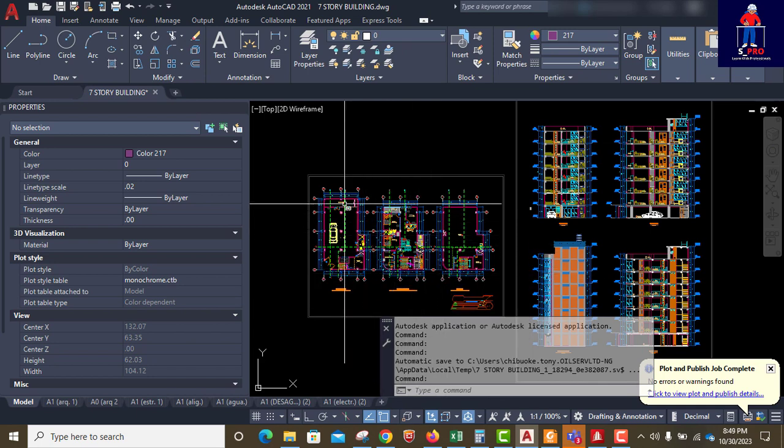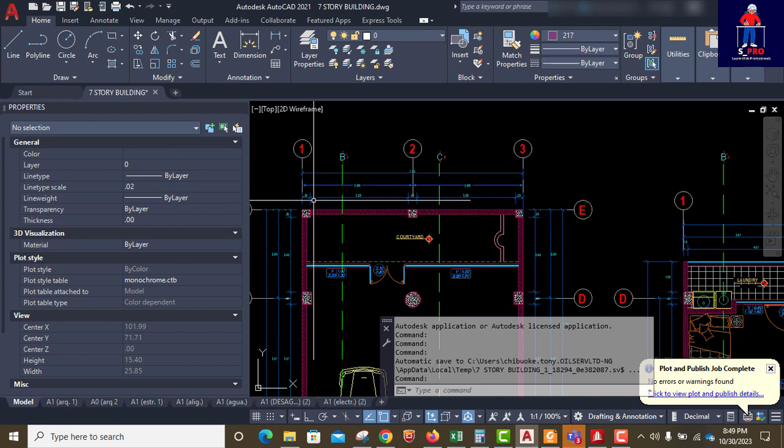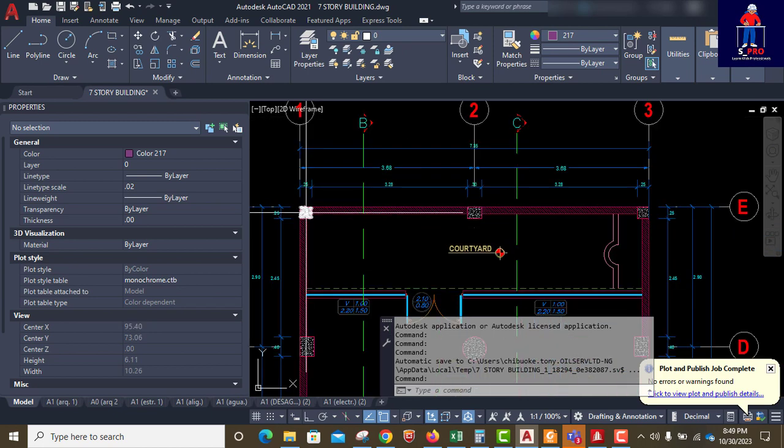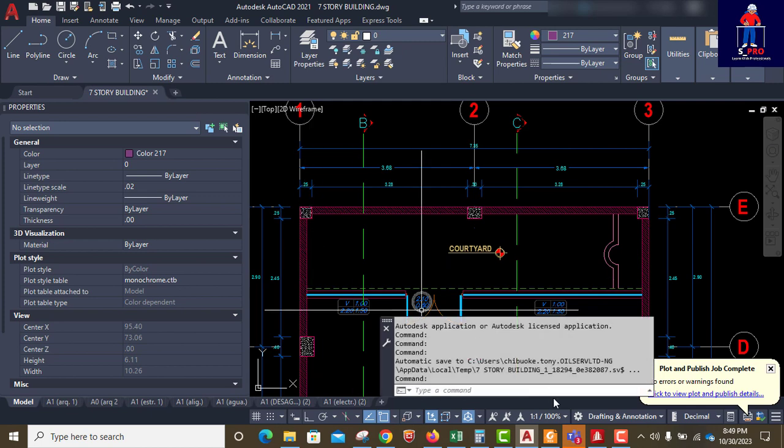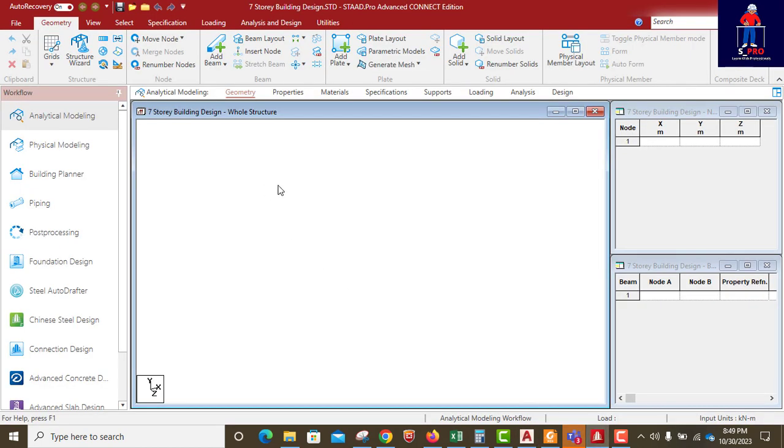Okay, so we start the model immediately. We are going to use this point as our origin, so it will be at our 00 level. So I'll quickly go to Staad.Pro. The first thing, like I told you in our training class, is to use this shortest format, which is using the node offset and copy paste to do my modeling.